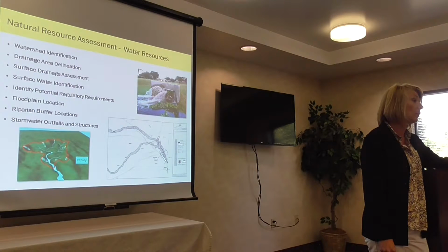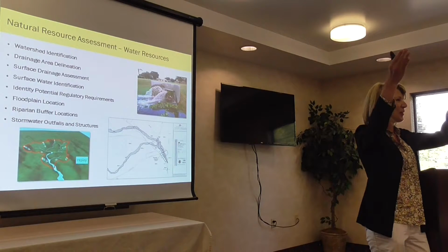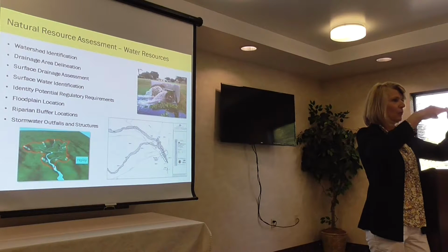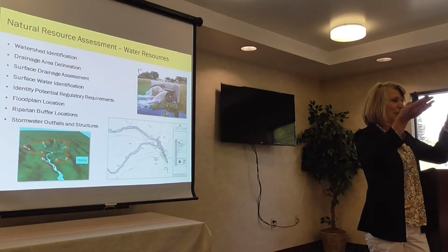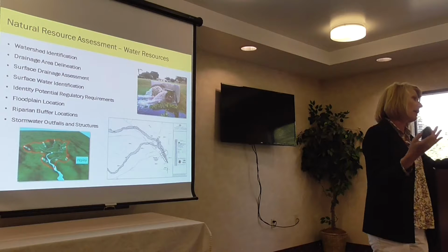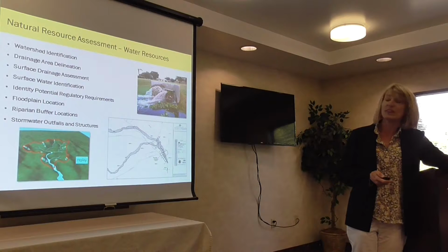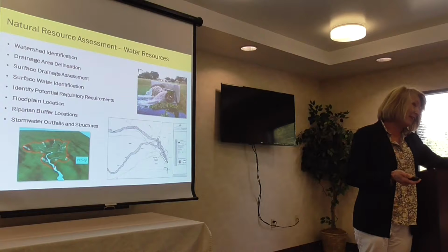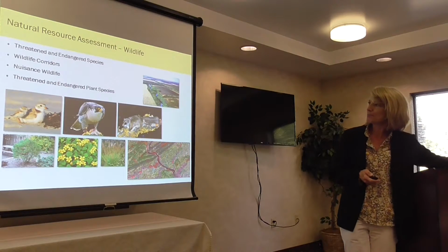It can be expensive, so we try to go through a process of elimination, going through One Call first, getting an idea, working with the municipality or the landowner to find out how much information they have on utilities, and then taking that and making some assumptions, and helping to guide where we want the private locator to go in and find those utilities. They can also size them, give you a better idea of how deep they are, the different utilities, and what kind of materials. So understanding those subsurface conditions is important.